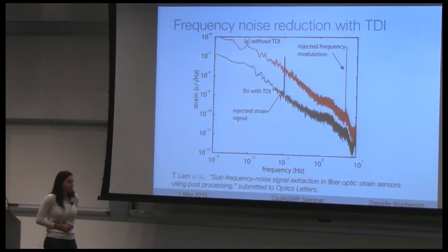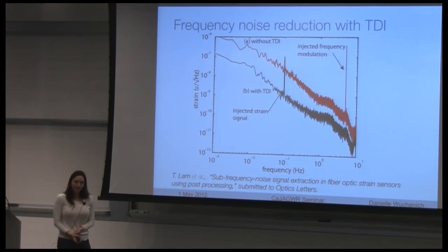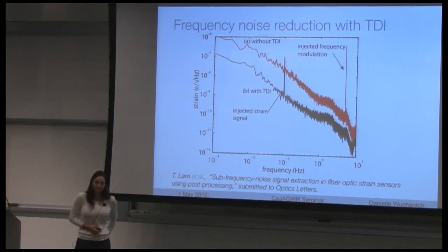At this kind of level, you start getting into your own limit of PRN noise, of code noise, where you have so many codes that you can only do so much averaging to get rid of all the unwanted reflections. Even though you want to pick off multiple signals, you can only average so well to a certain level, and that's usually around this level with these powers.